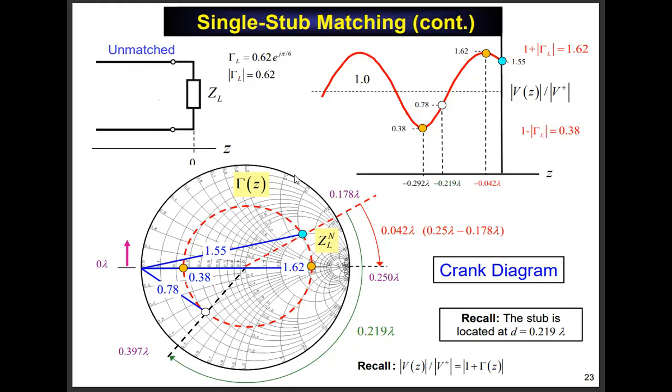Okay, don't forget that. But anyway, if you do that, and this was a real problem, you've got your ruler and you measured, supposedly this length here comes out to be 1.55. So that's what's labeled here. Right at the load, the normalized voltage is 1.55.